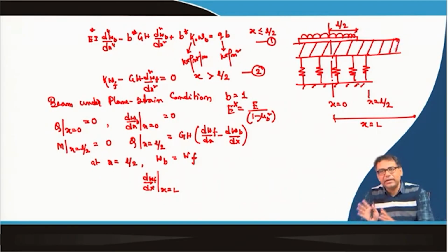Then how will you decide this L? Again you have to take different L and run the program, and you will find that after a certain length your deformation at the center will not change significantly, or will be within the tolerance limit. So, you keep your domain according to that. That means you change the domain L value, and you will find that after a certain L value, if you increase the L value further, your deformation at the center will not change significantly.